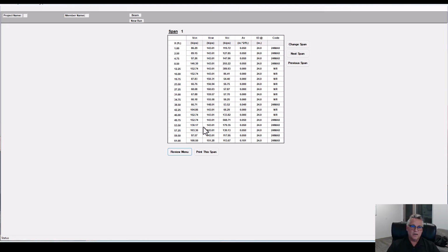So the beam shear design, your VCN, VCW, and VCI values. Try to recall if you can, but we did that at h/2 from the first interior support on the controlling side. So we calculated a VCN value close to 97, I think it was 97.6. We calculated VCW 143.6 or something very close, and we were at 118 on VCI. We decided that that 118 controlled the design. We used that and came up with stirrups, number 3 stirrups, 2 legs at 24 inches on center. This is where all of that gets checked and verified.